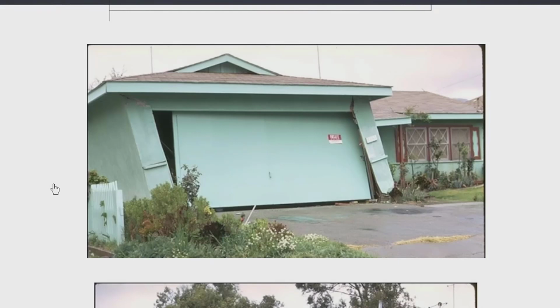And the roof is just a garage roof. It's actually quite light. And you can imagine if there was a house up here, what would happen? The house is rocking back and forth, and the walls on either side of the garage door opening, which are fairly narrow, are going to want to overturn.